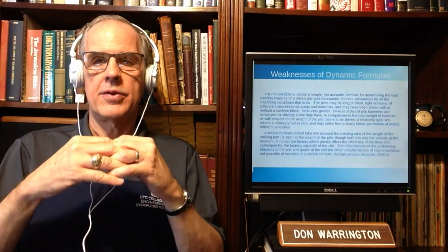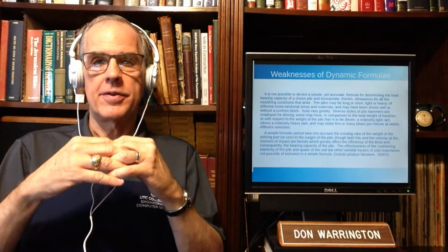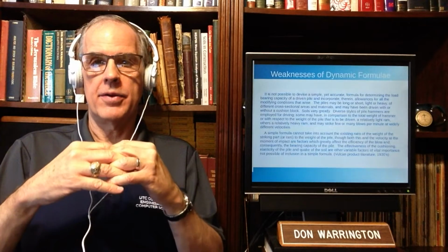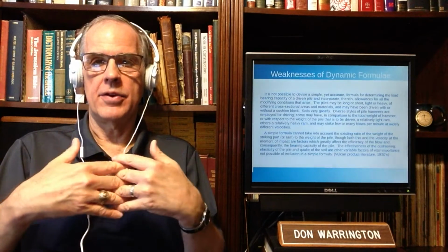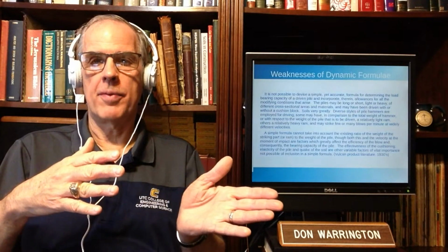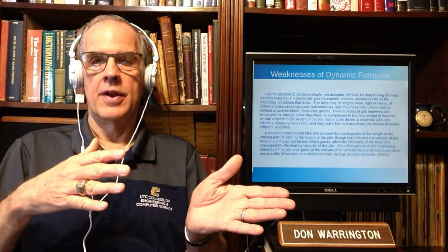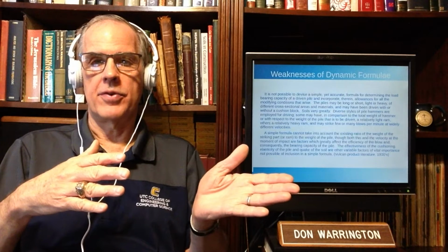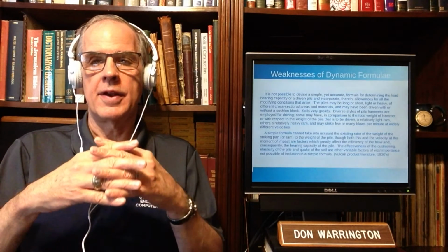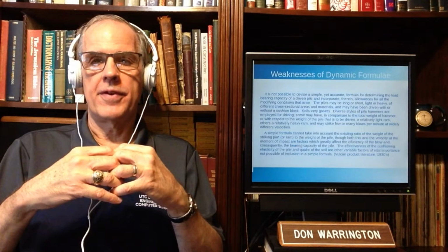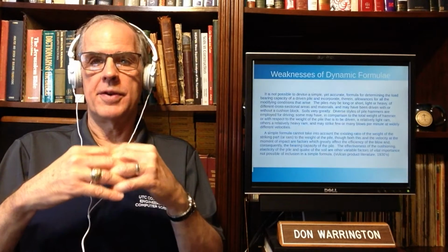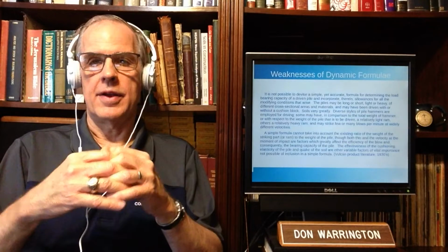They do not take into account the dynamic compressibility of a pile under impact loading. And then there are others after that. We talk about the properties of the soil response and other things. But for impact pile driving, the dynamic compressibility of the pile is the number one issue.